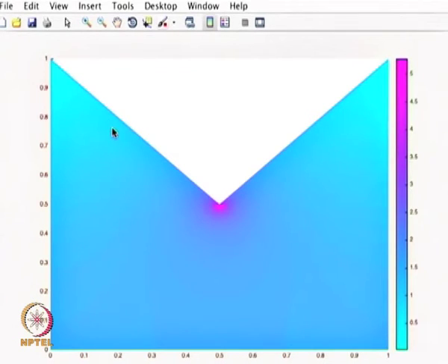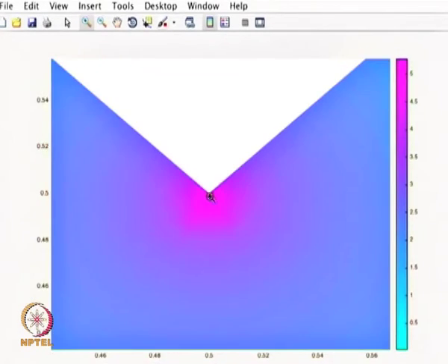Whereas if you see the way the electric field is plotted, overall we get a very good result, whereas what we see in the tip is the singularity is very sharply reflected. What you see is a value that is more than 5 in this case. In the coarse grid what we got is roughly 2.5, whereas in the fine grid we are getting a value that is more than 5, which is ridiculously wrong.